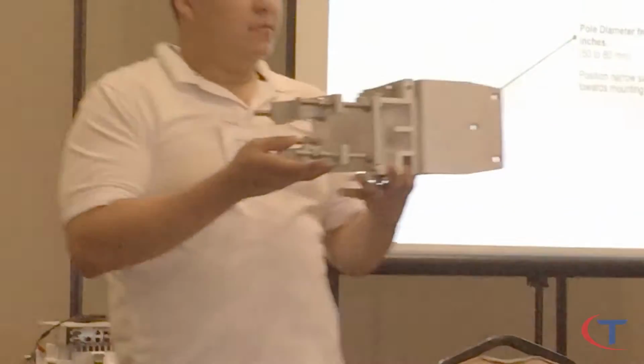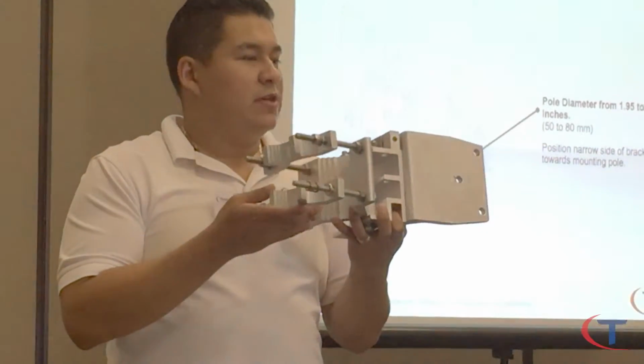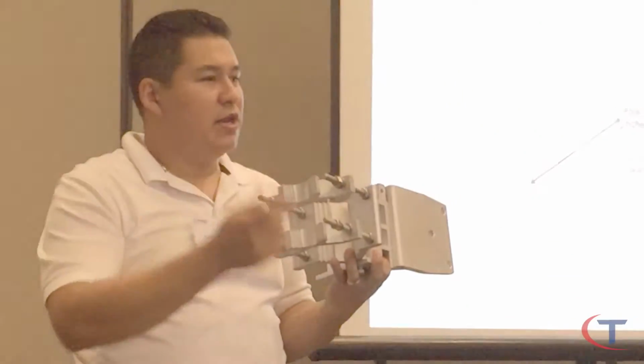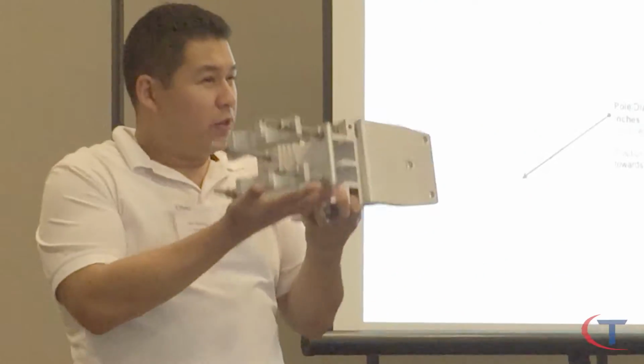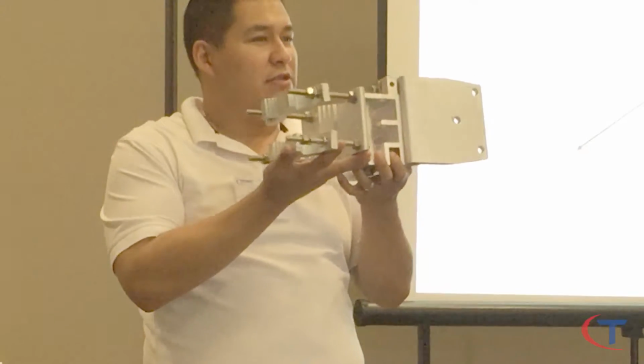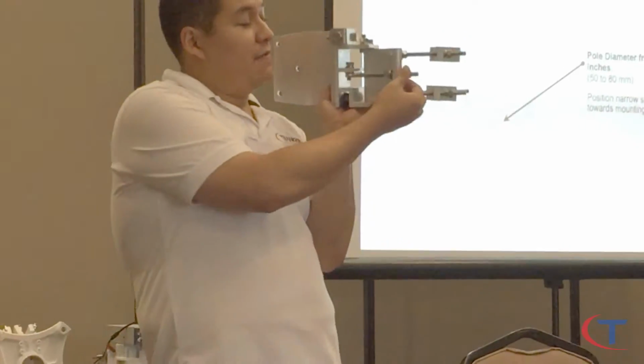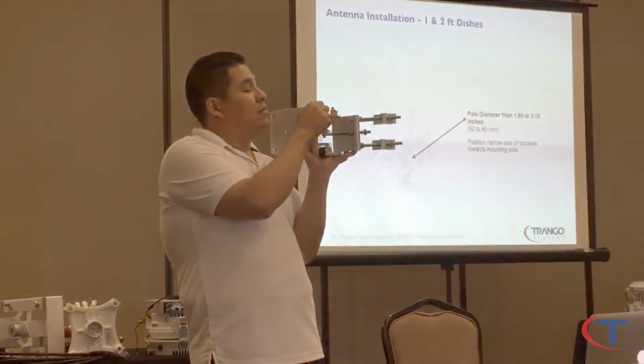And rough alignment, left to right. What we said before, little trick, self-tapper on the pole, nothing major, just a little 1 inch, 2 inch self-tapper, just to hold it in place because it's going to get really heavy with the antenna there. Then fine-tune adjustments on the back. We can have here this azimuth and then the actual elevation.